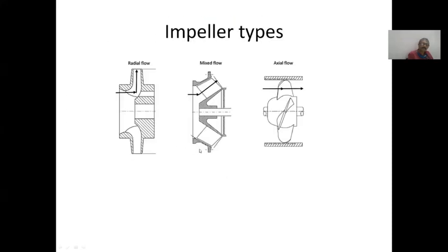And for pump selection, you should also know some basics about pumps. And you would have studied in your pump course that there are different types of impellers. One is this impeller, this another type of impeller, this another type of impeller. It's a radial flow. In radial flow impellers, water comes axially into the eye, then it turns direction and it moves radially out. So these are called radial flow pumps.